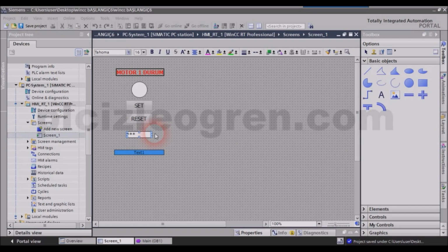Let's say there is a problem and you want to see the level of pressure, or you want to increase the value of the level of that pressure. You can enter any pressure value in here and send the command to your PLC, and you are able to perform that operation via the related field elements.